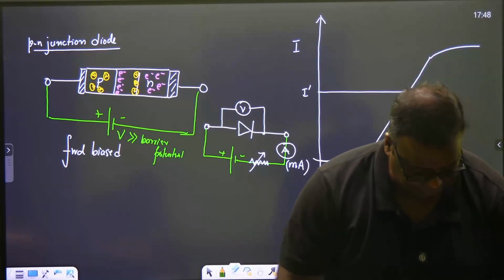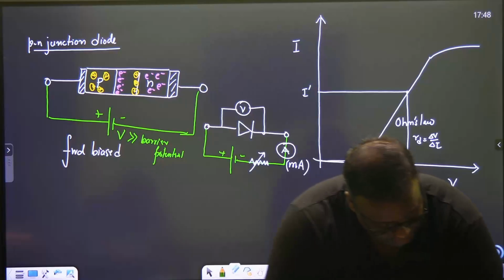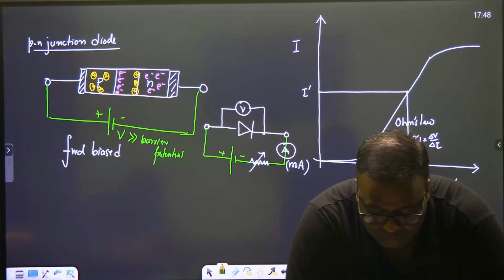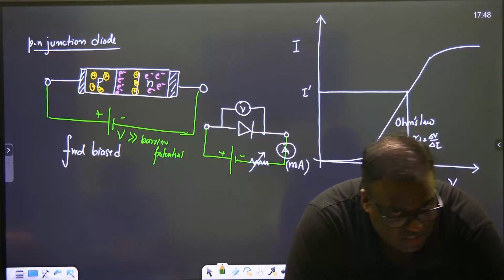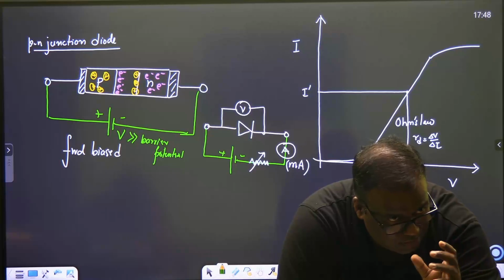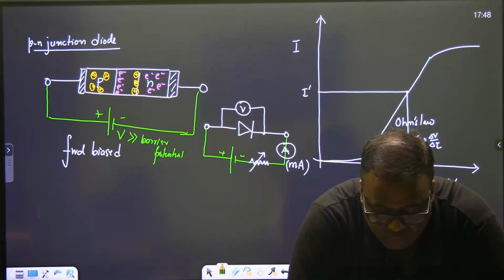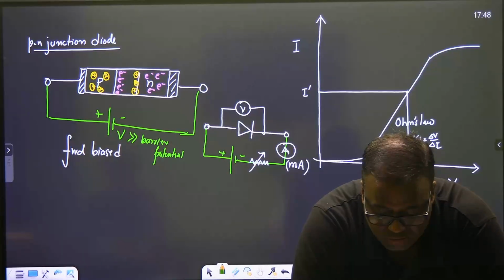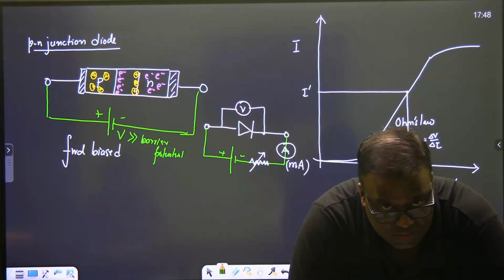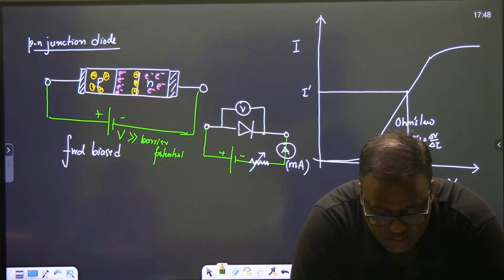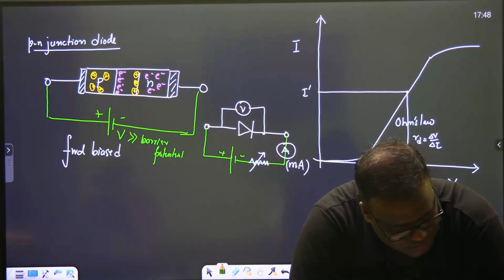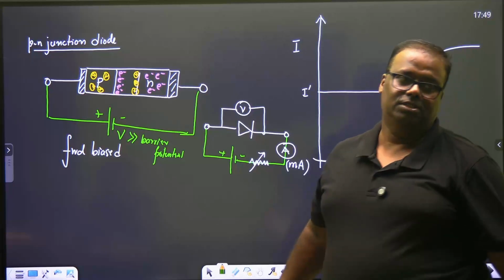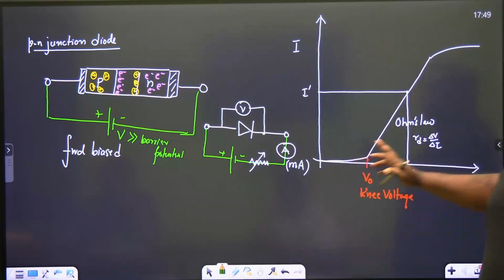Just listen to what I say. So forward bias, terminal connections, you know. Now recombination will stop. Now if a battery can overcome the potential barrier, current flow can resume. So initially there will be some current flow, then the electric field will come up, then no more current flow. In forward bias mode, majority charge carriers in both sections are drawn towards the junction. Negative repels electrons in N and positive pushes the holes towards the junction. Right? Free electrons and holes combine at the junction. For each combination, one electron is pushed to the negative terminal on the N side, and one valence electron leaves the P side and enters into the battery. That's all. Right? Remember one thing, you get a very good current when you forward bias the diode.